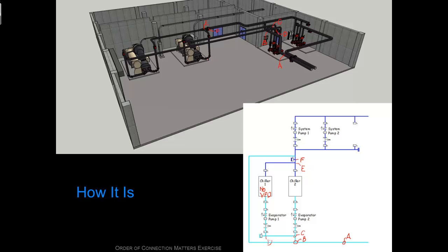So sure enough, I come through the service valve, go through the chiller, come back out of the evaporator, and go through another service valve, come up, drop down. I'm on the discharge side of the pump, so there's a service valve and a triple duty valve there and a pump, through the suction diffuser, and I come out through a service valve, and I end up back at point C. So now I actually have most of this circuit, or that complete circuit, traced out.